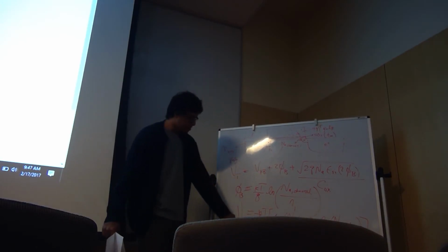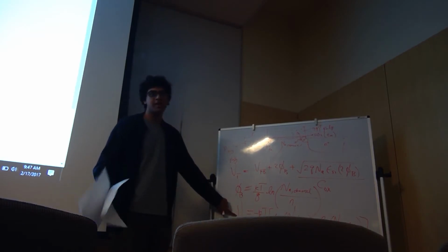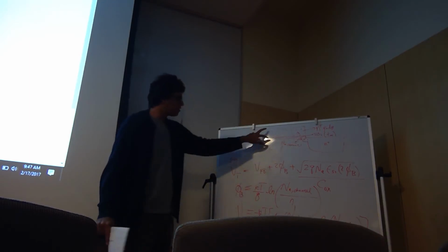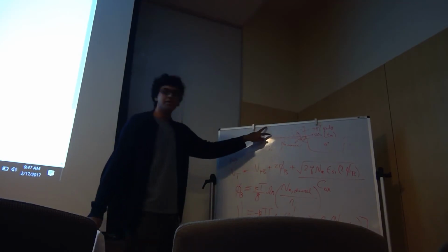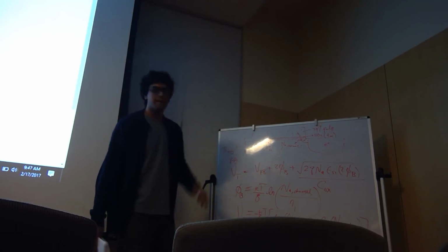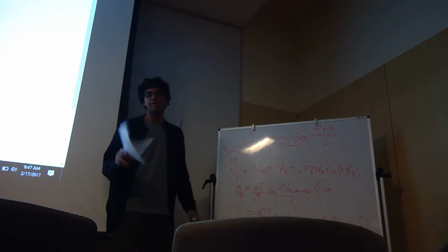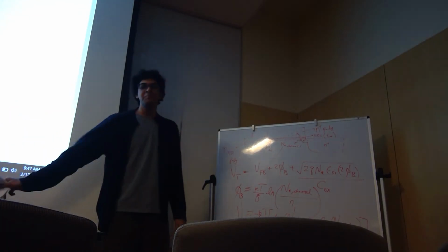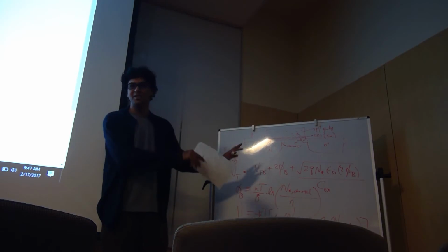This flat band voltage, you need to understand how to calculate, and I'll go over that if I have time. This will change depending on your doping here, okay? The flat band voltage generally depends on what material you choose your gate as. So if you choose a metal, your flat band voltage will again be different. But I'll go over this if I have time. And please remember, these equations are for the NMOS, and the equations change for PMOS, okay? So you can refer to some material to figure out what the PMOS equations are. These are available online. You can search for these formulas.